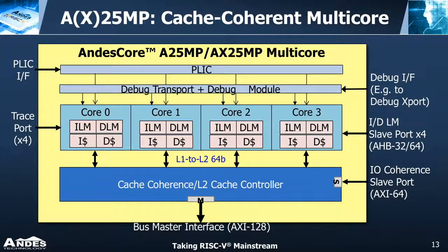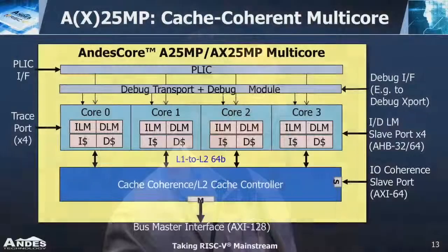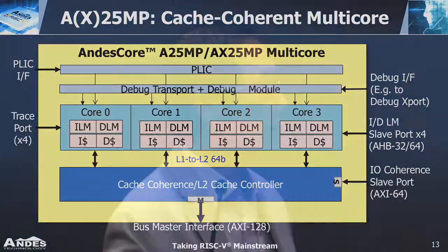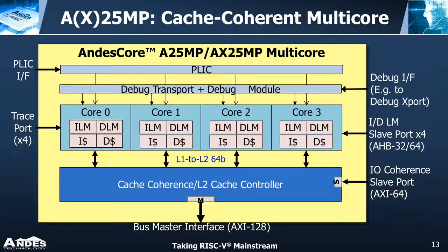So when there's a cache miss, the unit will track 8 different address sequences and prefetch up to 8 lines, making the performance maintaining still there. The other, for instruction prefetch, it is also like this. After a level 2 miss, it can prefetch up to 3 lines. So for instruction and data, they both have the prefetch feature.